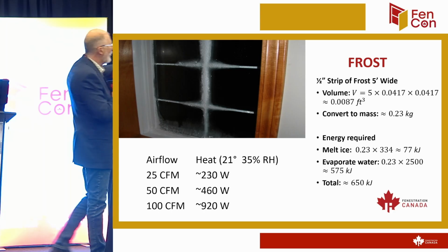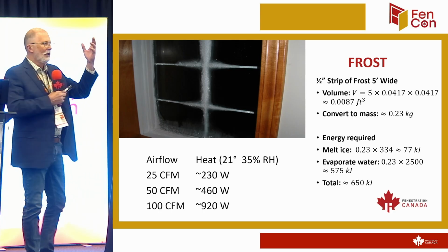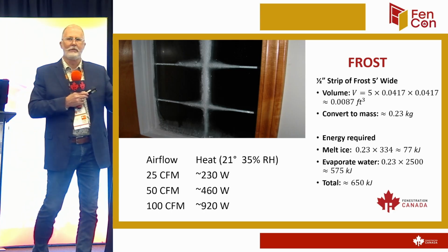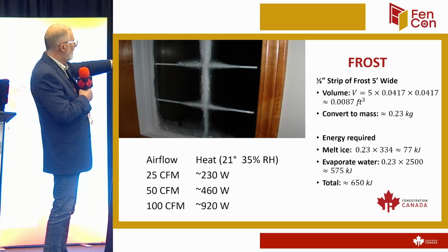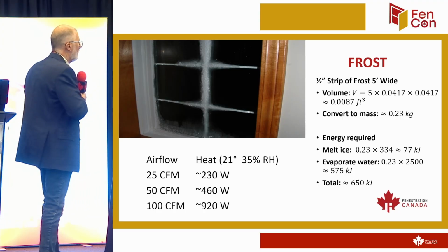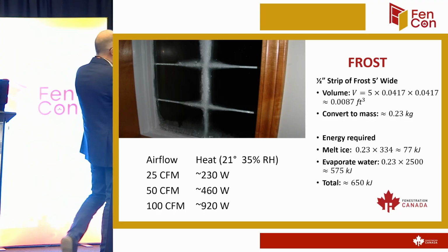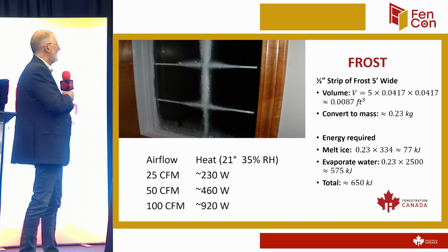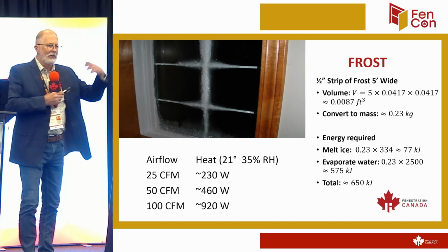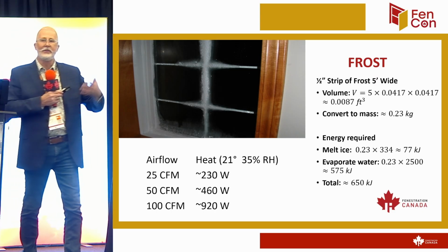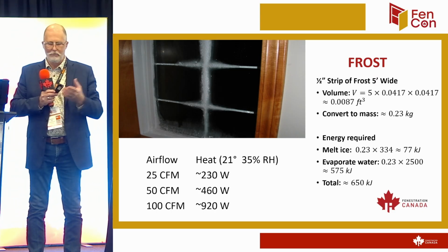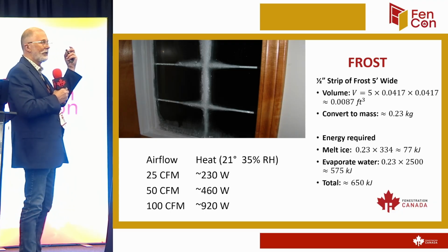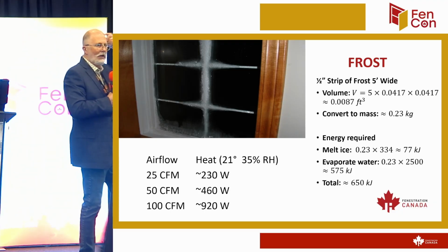So if I look at standard airflow, how much energy is in the air? If I put 25 CFM of air towards that window, I get about 230 watts of heat. If I put 50 CFM, I get double. 100 CFM, I get double again. It's just the amount of energy that's in the air to melt that and evaporate the moisture off of there. It's no different than taking a hairdryer and drying your hair.